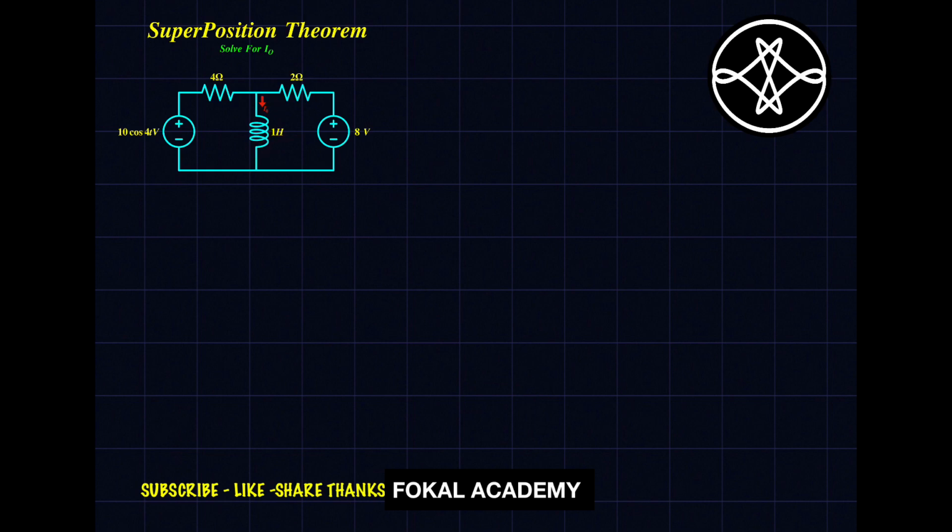According to the Superposition Theorem, each source has some contribution to the current. Due to this source there is some contribution to the current in the inductor, and this source also has some contribution. Let the contribution due to the DC source be current I1, and due to the AC source be current I2. Here I1 and I2 enter in this direction.